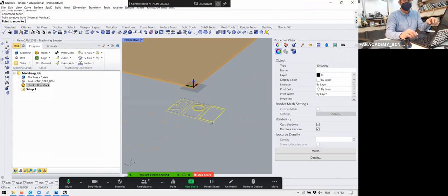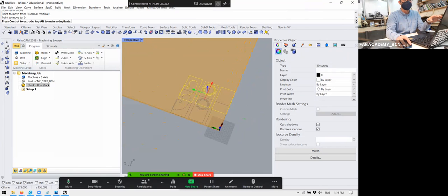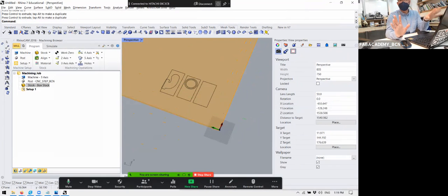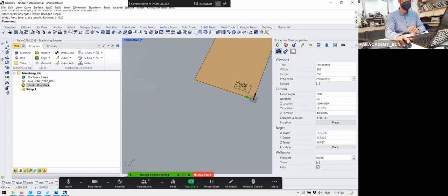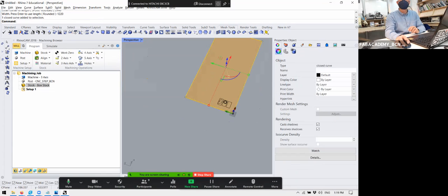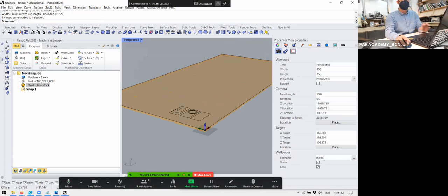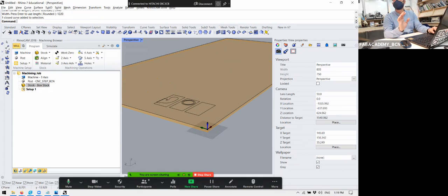So what I do is, I know that this file is flat. I locate it in the origin, and now I move in a safe way. This is my personal workflow. It has worked so far for about 9 years. I draw a rectangle the same size as the material, just as a guideline for me. And I know I will always put screws in the corner.